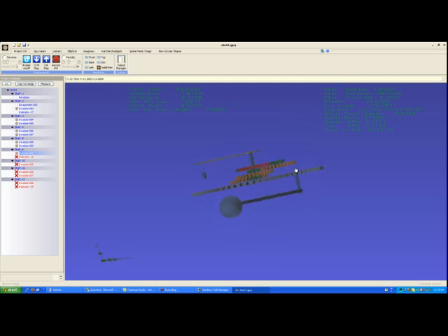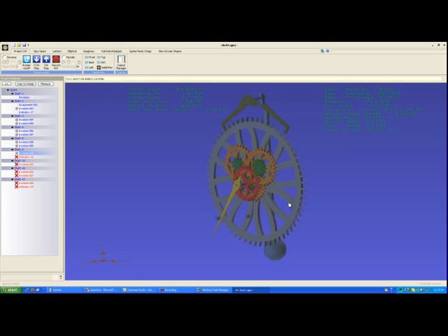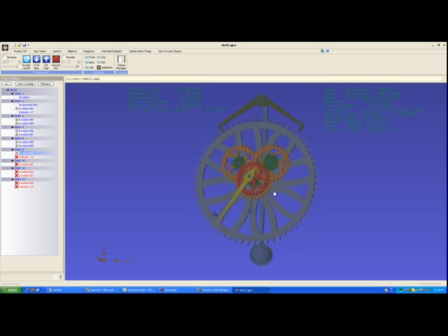Okay, so what happens is when you place this 14-tooth gear just above that other gear, nothing special will happen. When we go to place our 30-tooth gear and we rotate it to center, we'll be asked a question, as we have been asked with all these gears that match on a shaft. It will say, I have found the center of a shaft which is very close to what you're trying to place. Do you want me to use it? From this version forward, you should say no if you're building a clock.